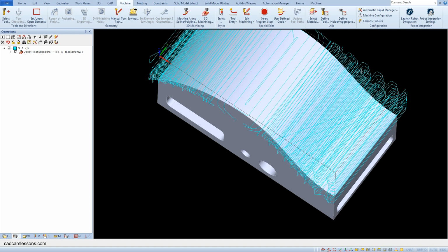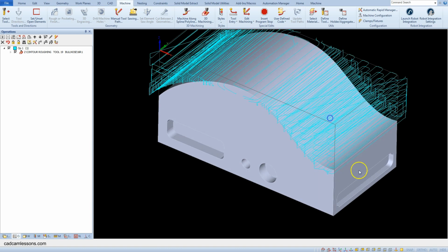And these fillets will be added for all sharp corners, all toolpaths, and this option will change the cutting direction smoothly. In the simulation this option will not work, but it can improve the machining process on the CNC machine. Okay, we have rough machining ready, so we will now proceed to finishing.